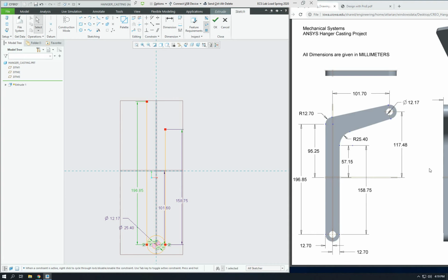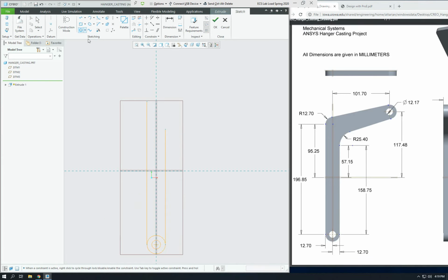Okay. Now the next thing is this circle, which is the same size as this one. Click on here. You see, when I click here to make a point, and then when I expand this, you see every time it snaps at some point. Here there's a sign equal, which is a constraint, and it makes this circle equal to the circle at the bottom. You see the circle at the bottom is green right now. When I move this a bit further, it creates another one equal to the second one.